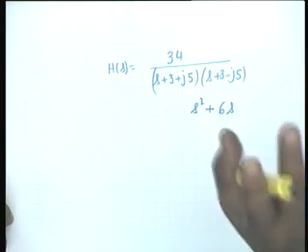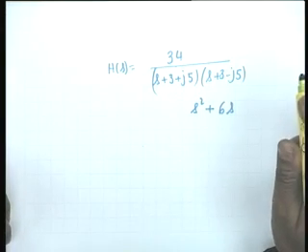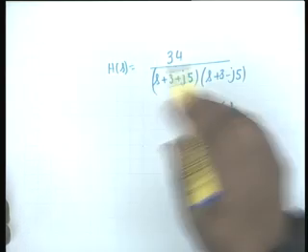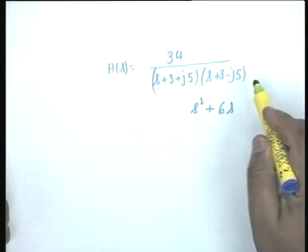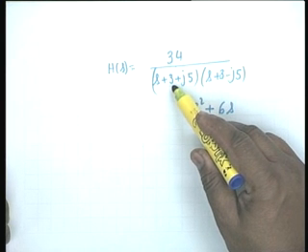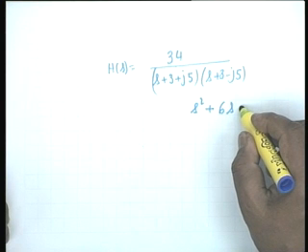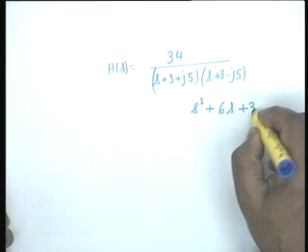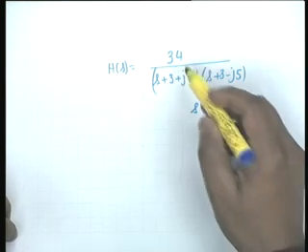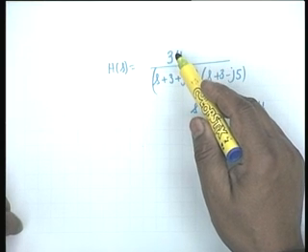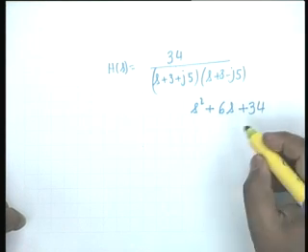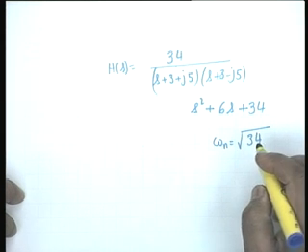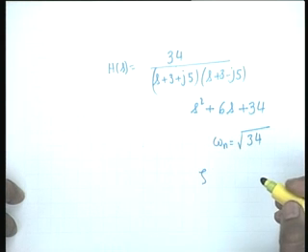Okay, you settle this controversy and let me know in the next class. That is why I left a question mark. Okay, here, come back here. This is how much? 9 plus 25. Is this 34? 25 plus, yes. It has to be 34, there is no other way, because the numerator is 34, omega n squared is 34. You can also find out from here what is omega n. Omega n is square root of 34, and you can find zeta.